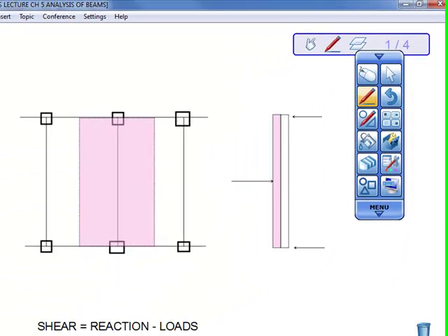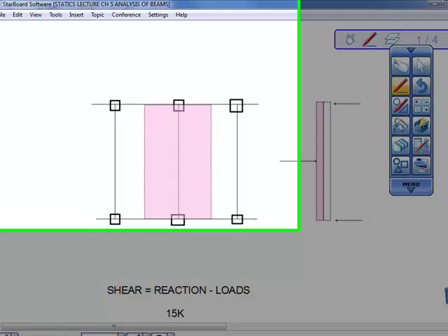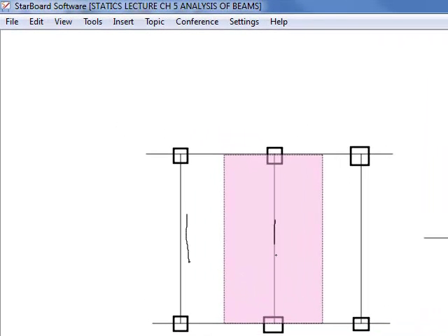Anywhere, people could be walking there, it could be 100 pounds per square foot. So they have to design it for that. So this distributed load, you got a beam here, you got a beam here, and you got a beam here. So this 100 pounds per square foot has to take care of this shaded area right here. So when you draw your diagram for that, and I'm looking sideways so I can line it up, you've got your beam, and then they've drawn their distributed load at 100 pounds per square foot.